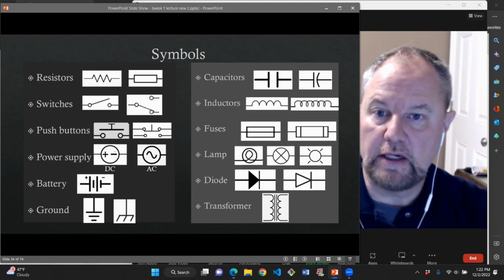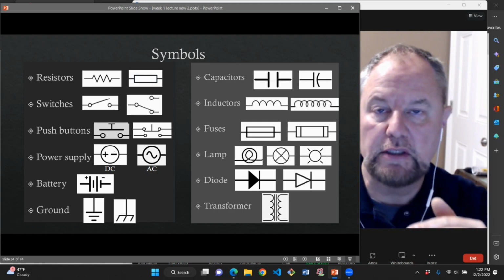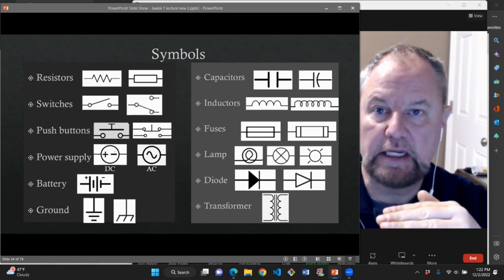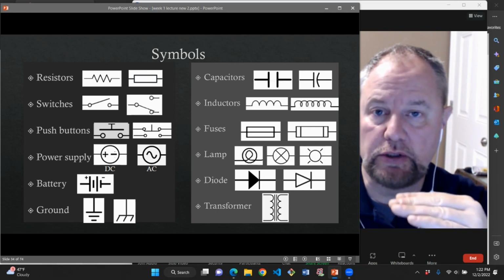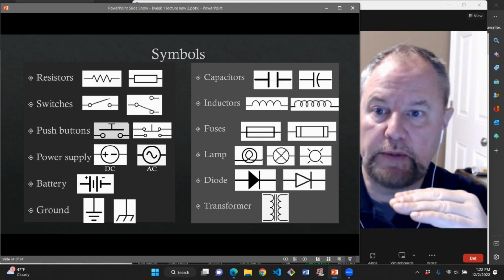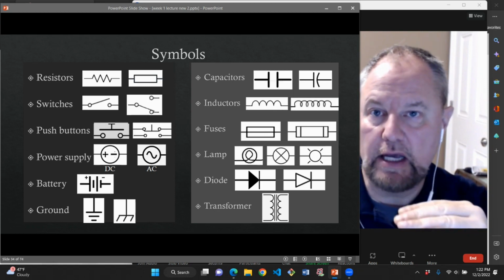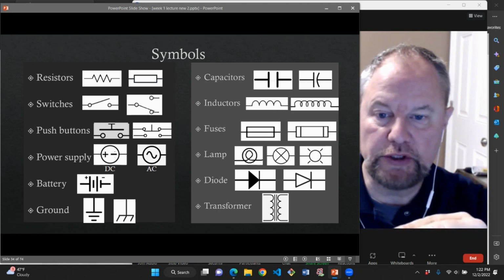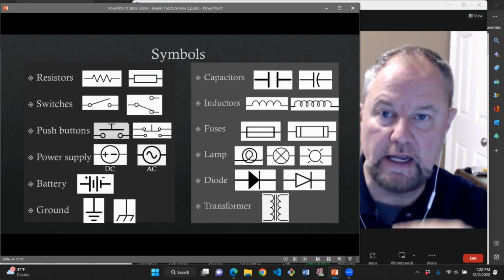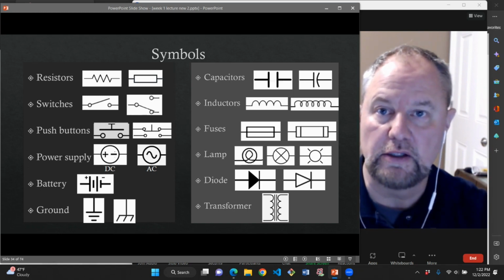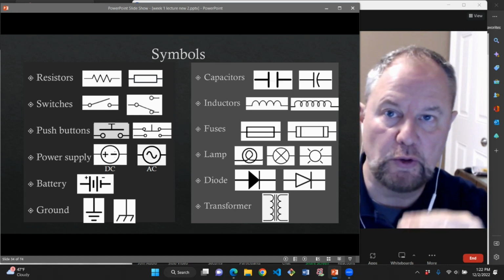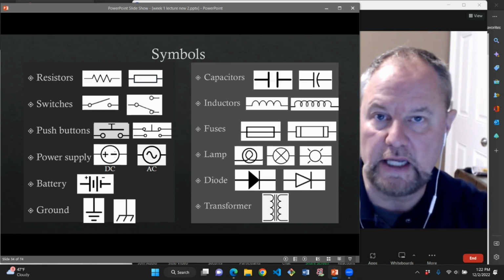The one to its right, if you notice, the button, when unpressed, is actually connecting those top two terminals. Those would be considered your normally closed contacts. Then when you push the button, it's going to disconnect those top two terminals and connect the lower two terminals together. Those are considered your normally open contacts.